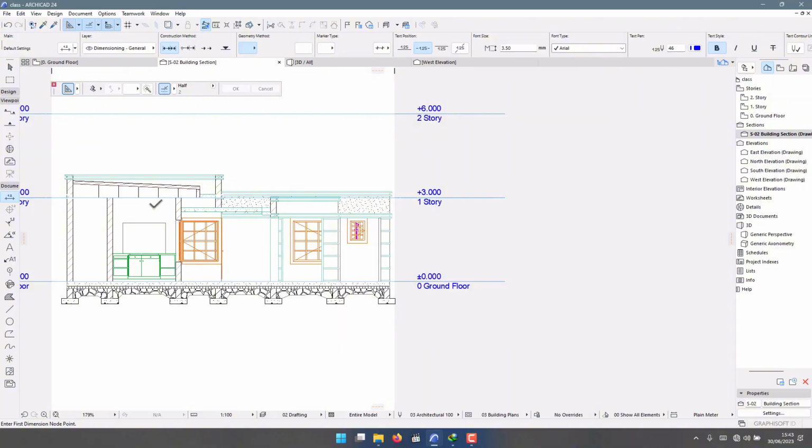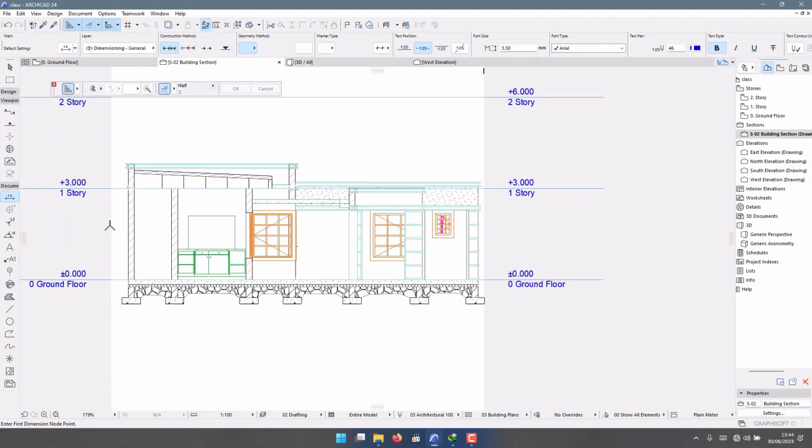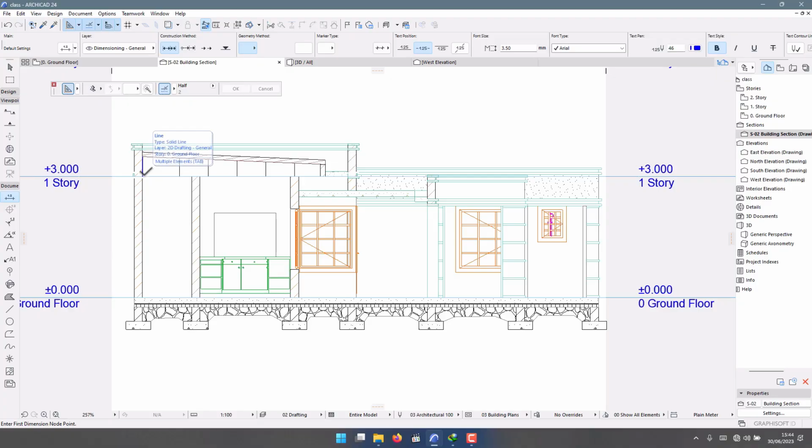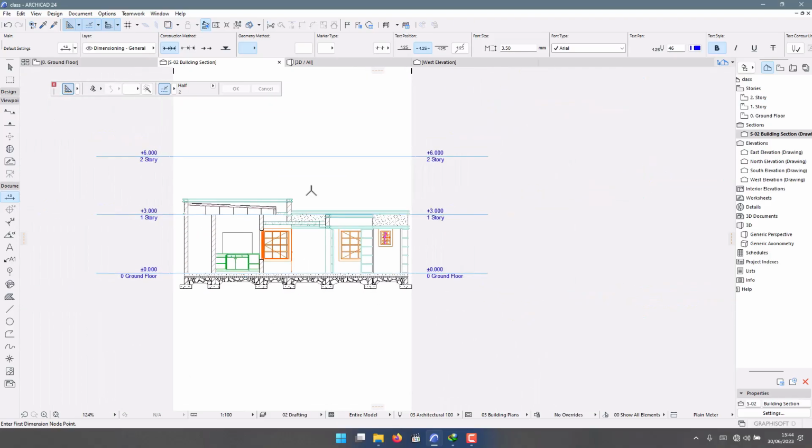I see people's drawings, and when they are trying to build a structure they don't have the height, so they have to guess, and usually they will guess the standard one, or sometimes they will go with where they run out of stones, masonry blocks. If they run out of masonry blocks before they reach 3 meters, then they end it there. So whenever you're doing a drawing, make sure you indicate the height of the building in the section.